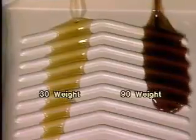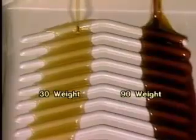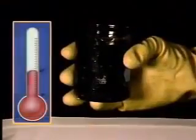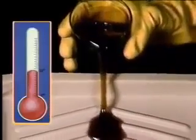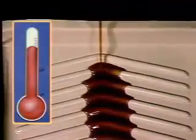Viscosity is greatly affected by temperature. An oil's viscosity, or thickness, increases as the temperature drops. The colder it gets, the thicker oil becomes and the less easily it flows. As the temperature rises, viscosity decreases. Oil gets thinner and flows more easily.